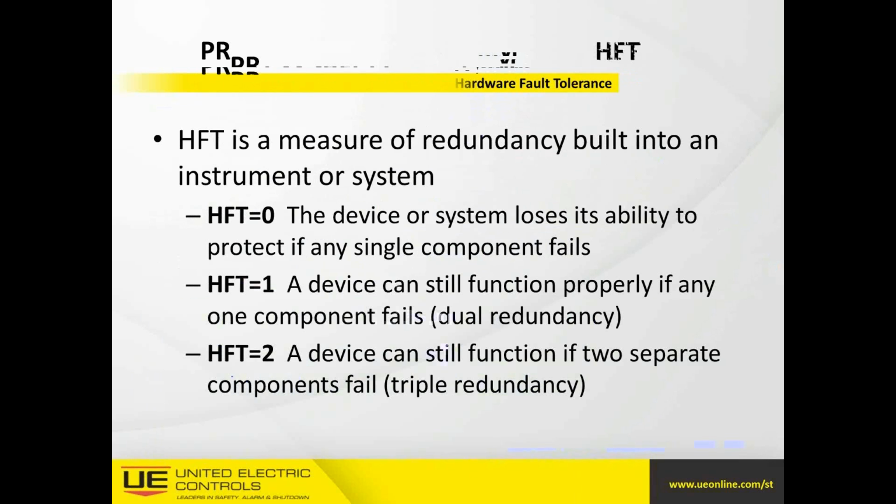and by the way, those numbers, the risk reduction factors and some of the other, the failure in time, the probability of fail on demand averages, all of these numbers can be found from a manufacturer's FMEDA. So failure mode effect diagnostic analysis are where these numbers are found, and those are the numbers that can be used in the calculations. We'll look at some of that here in just a bit, but wanted to let you know that.